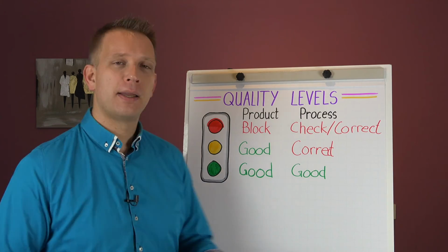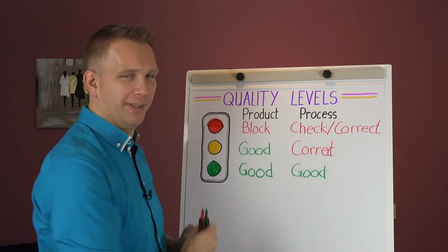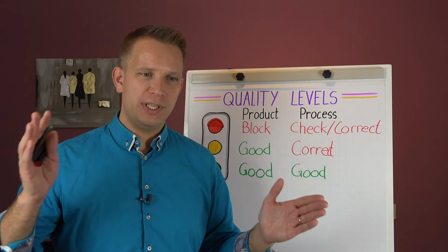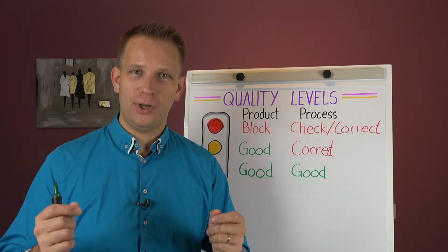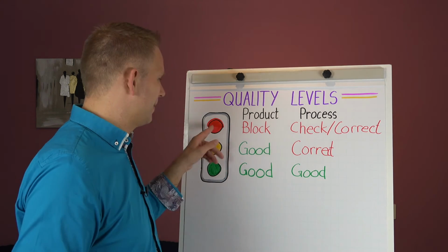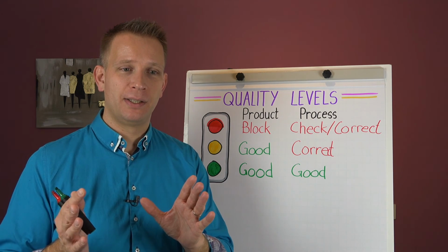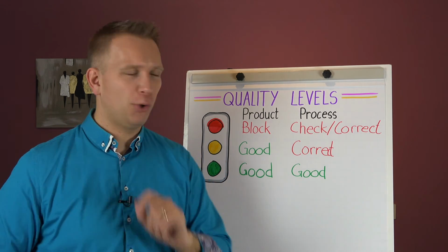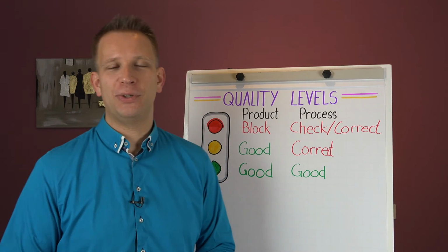And this way gives so much more clarity than putting product only specifications there that for some reason have this orangey zone in the middle. I never know what to do with an orange product zone. Is the product good or bad? Do we need to correct it or not? Red and deep red, yes, we know how to correct it. Or we'll have to see, but they are both corrections. And the orange level should be reserved for process corrections where the product is still good.